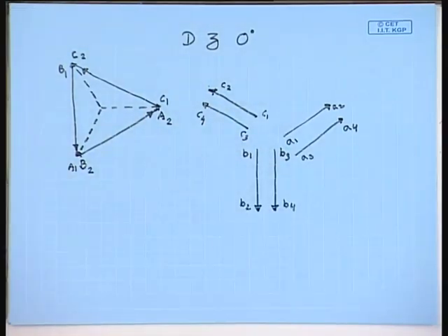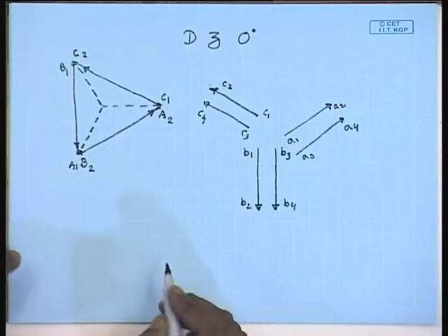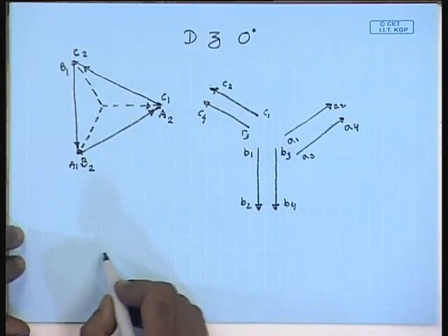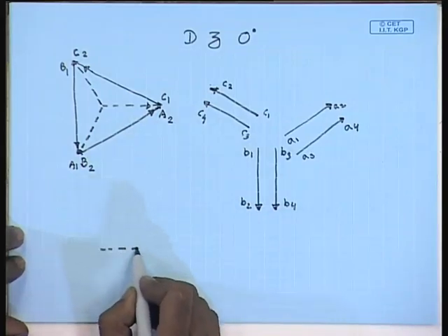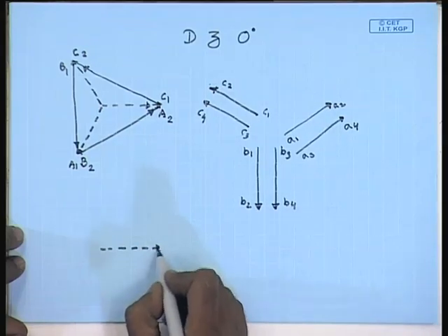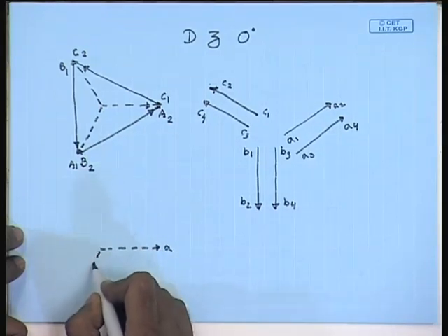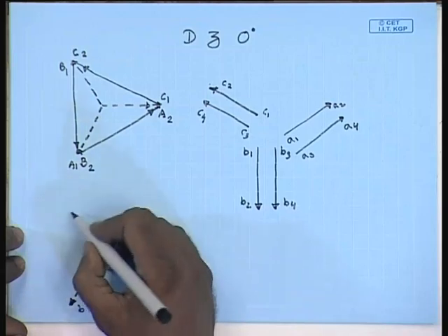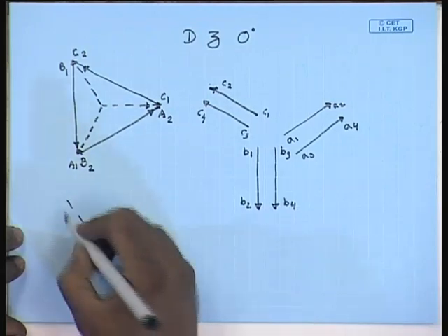It is necessary to make the connection as Dz0, which means that the zigzag side line to neutral voltage should be in phase with the line to neutral voltage of the delta side. Therefore, the zigzag side line to neutral voltage should be, this should be a, this should be b and this should be c.